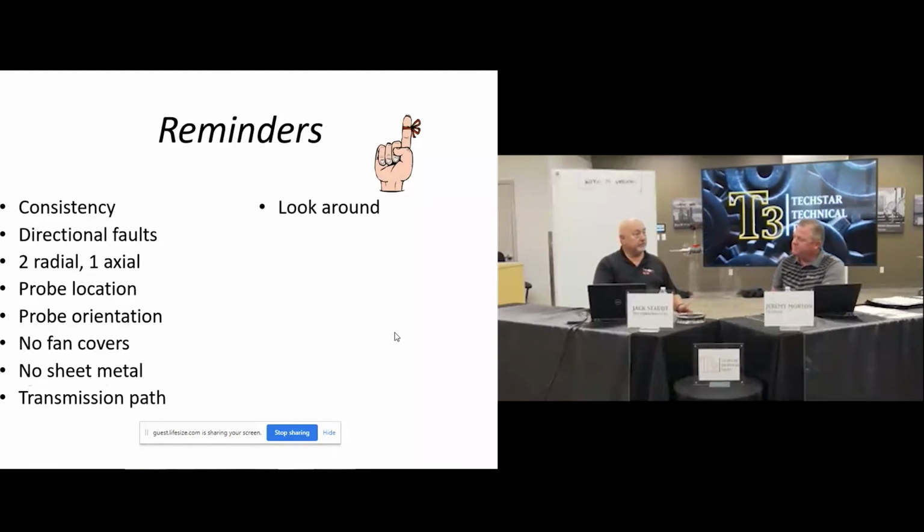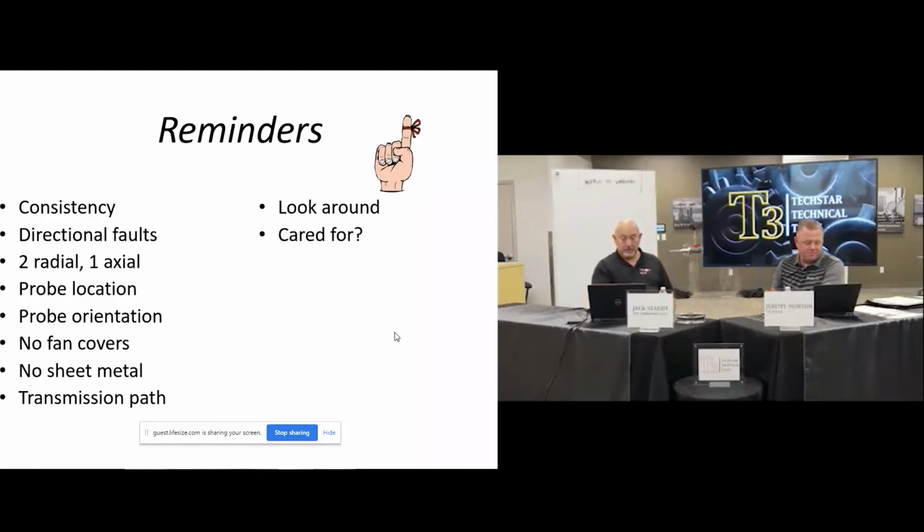Look around. Don't just be the robot out there collecting data. Just look at every machine, just kind of have some reference checks. Is there any leaks, or is a gauge broke on it or something like that? Foundation cracking under the foot. That's right. So pay attention. If there's grease all over the place, clean it up right there so you're not getting everything all on you.